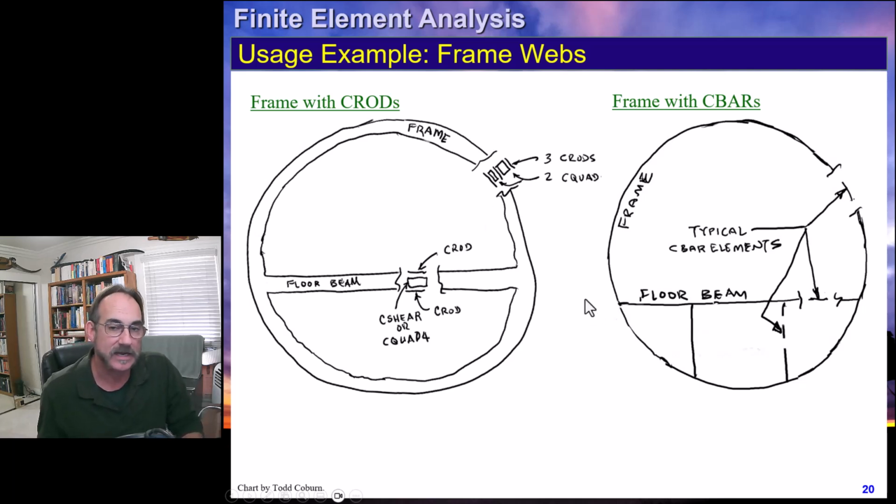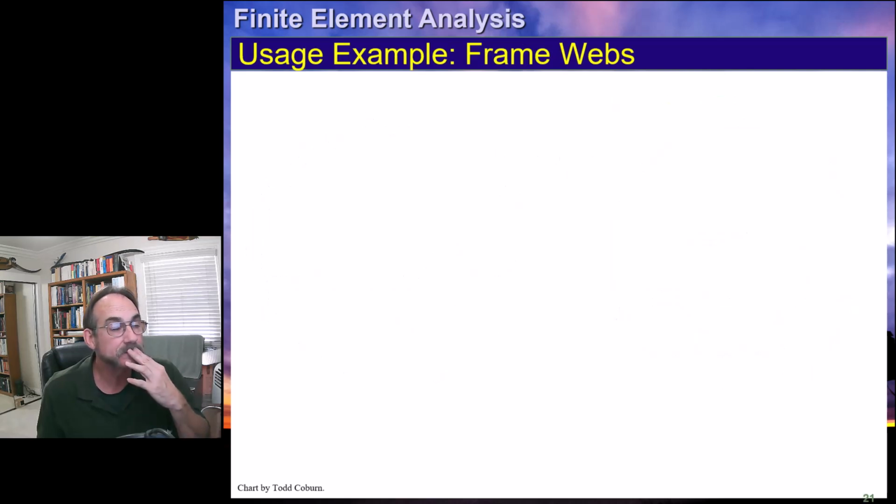And while it is trendy to overcomplicate the model and to make a lot of fine detail in simple models that would otherwise be simple, I believe the best approach for many large-scale structural models is a simple, coarse representation that accounts for the stiffnesses you need and some post-processing to support that.